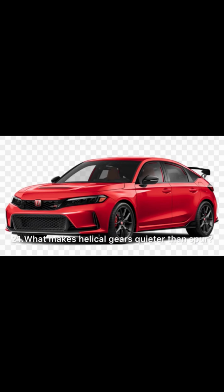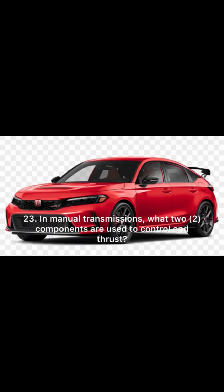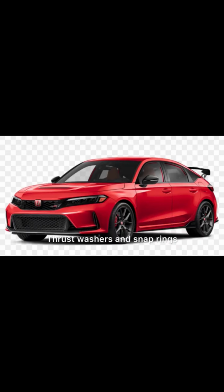21. What makes helical gears quieter than spur? Sliding motion in and out of mesh. 23. In manual transmissions, what two components are used to control end thrust? Thrust washers and snap rings.